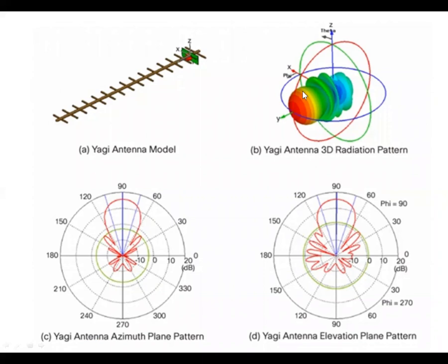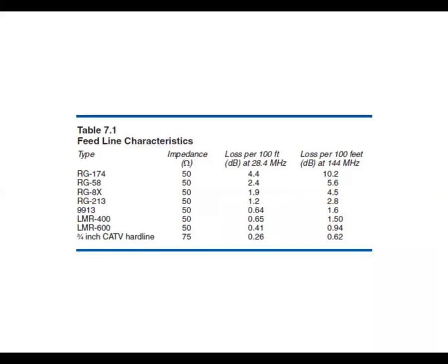You can see how this lobe here, you could spin that around like you could here, and do all kinds of neat stuff with single sideband. You could build a Yagi like this for 40 meters or 80 meters even, but it'd be huge. I think the cross members on 80 meters would be 40 meters wide, which is pretty big.